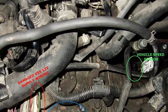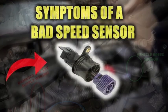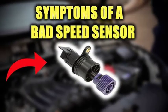Speed inputs and diagnostic codes (DTC). The VSS is one of many sensors that provide input to the PCM. Other sensors that provide speed input include the wheel speed sensors and the transmission output speed sensor. The PCM uses this information to calculate the vehicle's speed and to diagnose problems with the drivetrain.